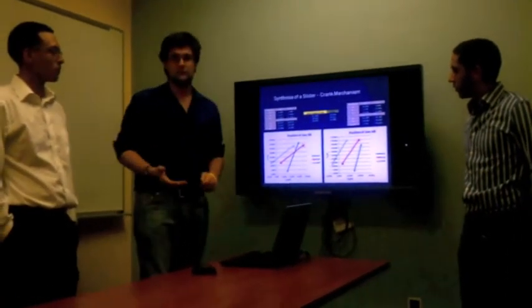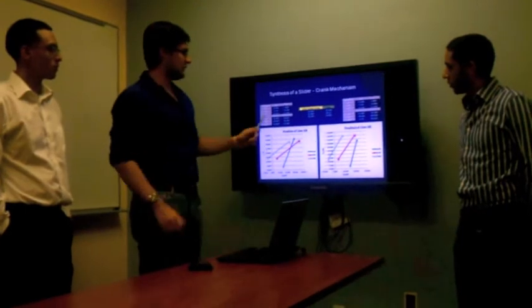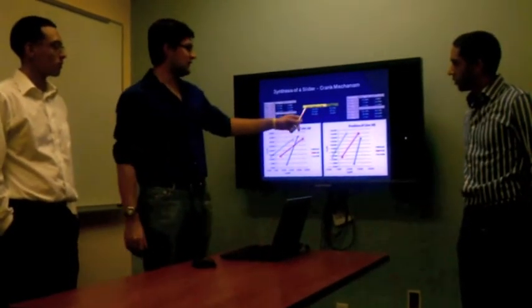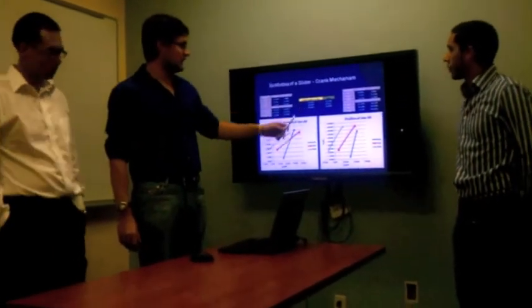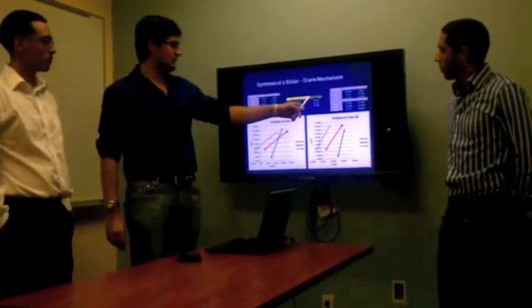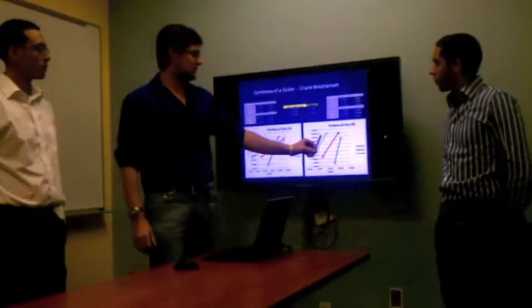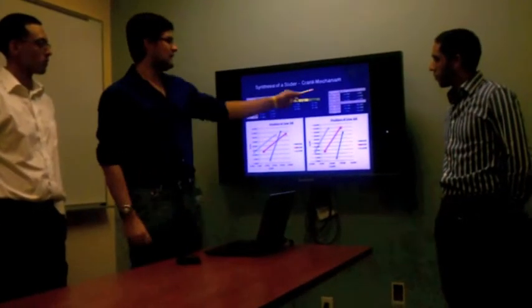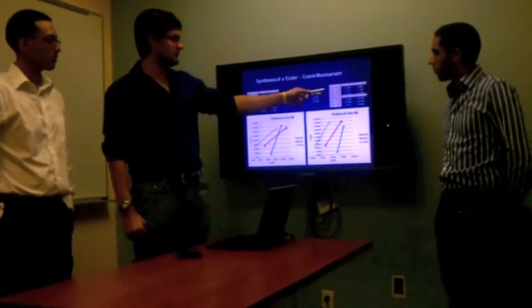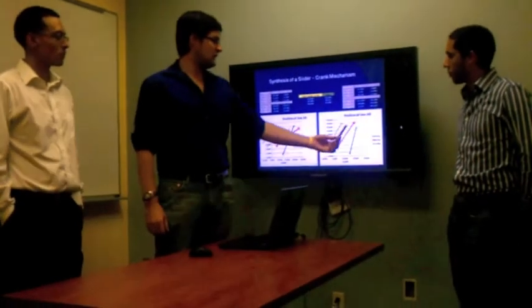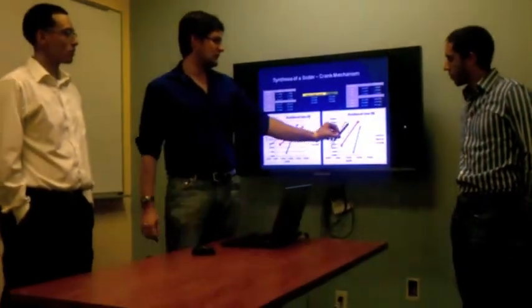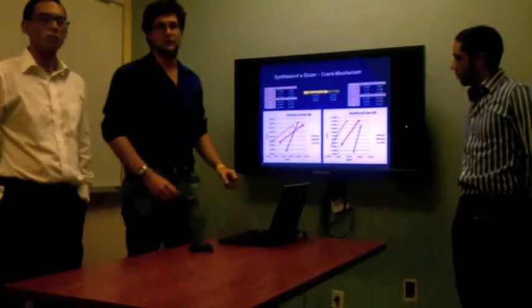So in order to correct this, our first plan of action was to make all the link lengths the same length, make them all 35 inches, and change them a little bit from the original, and then readjust the angles by keeping some of the A positions the same and changing the B. We altered the angles and allowed for the coupler link to move in a better flow.